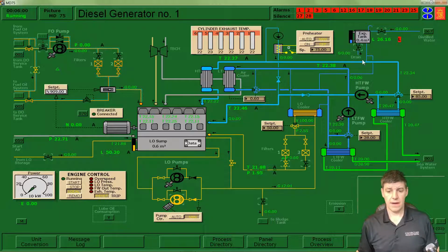Okay. I have my freshwater system, so this is sort of a secondary cooling system that is what I use to circulate water through the engine. And I want to keep it separated from the seawater system because the seawater system may be, let's call it, dirty or untreated water. And the freshwater system, I want it to be clean and treated water so it's suitable for going through a piece of equipment. So I want to isolate those two, and I do that using the freshwater systems.